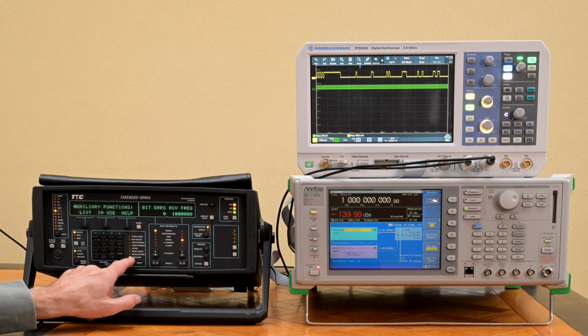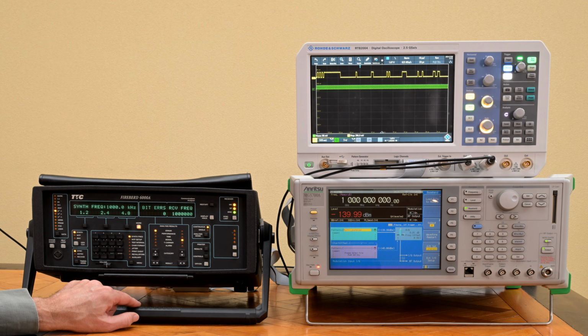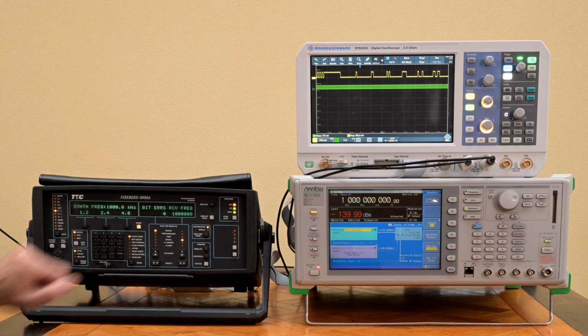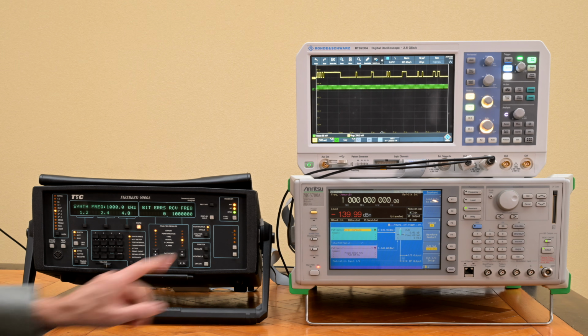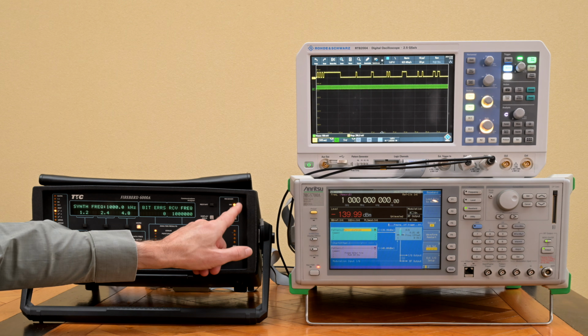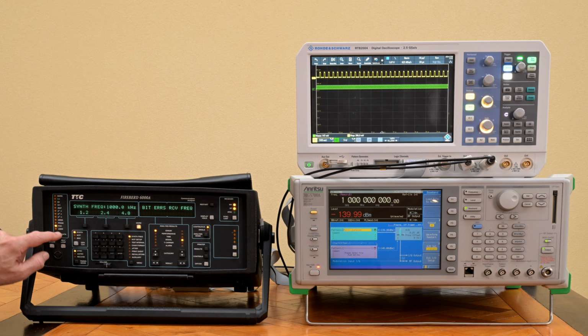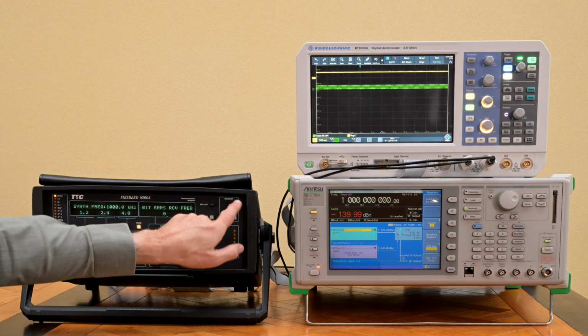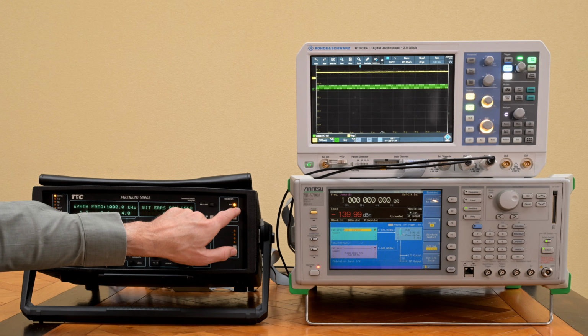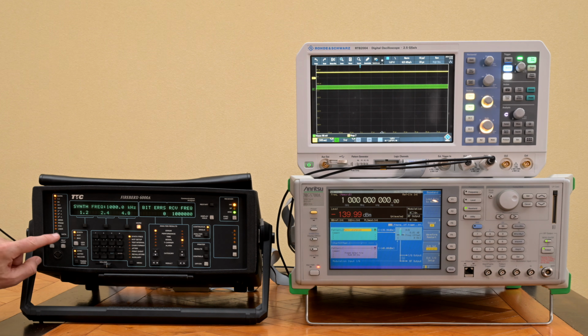We'll be setting here the internal synthesizer, and it's now set on 1000 kilohertz. That's 1 megahertz. Oh, that's quite okay. So I'll leave it at that. And I basically got my loopback already working, because I can see mark and space are both being received. Actually, if I would go to mark here, sorry, 1 to mark, I would only see marks, but there are no spaces. So there's only ones and no zeros being received.